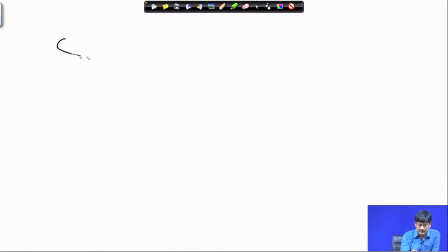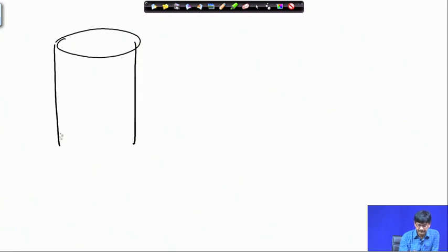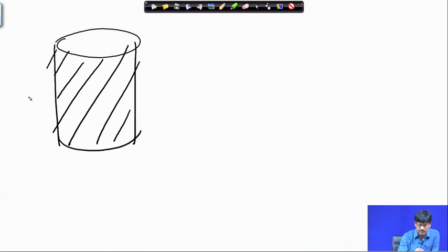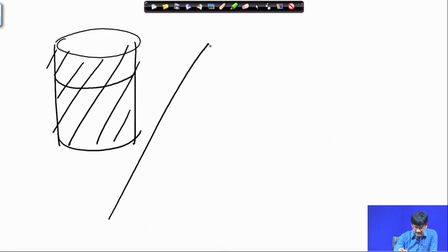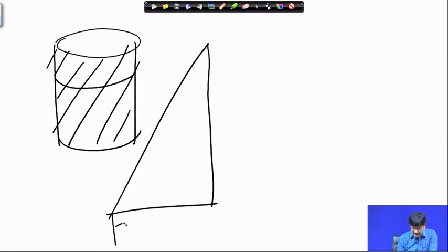First of all, if this be the gear, these are the helices. As many teeth as you have, so many helices. So, it is a multi-start threaded element, but we take only a slice of that, and this is our gear. If we unwrap a single helix, it would look like this. Where if we are unwrapping it, this must be pi d, and this is given a name, lead.